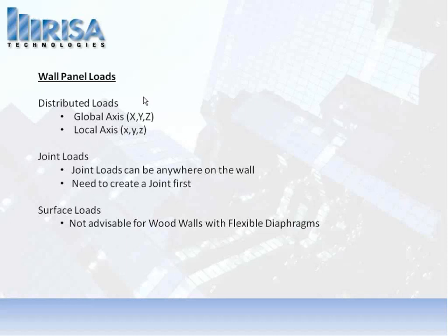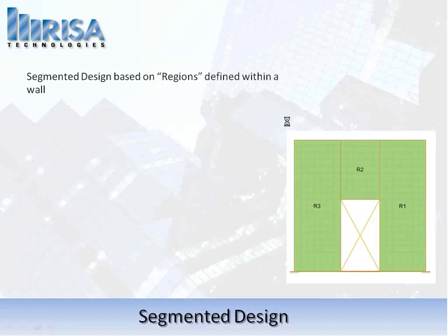So distributing loads out of plane, like for example, if I was just sort of blanketing wind load on that, it may actually push it out of plane too much with a flexible diaphragm. Maybe with a rigid diaphragm it would help us distribute the loads a little bit, but with a flexible diaphragm there's actually no real diaphragm behind the scenes, it's just a distribution of loads. So we'll talk more about diaphragms a little bit later, but the issue of surface loads, it can be done, but definitely you want to be wary and take a look at the results and make sure you're not pushing that wall over and not having enough stiffness there, okay, because there's very little out-of-plane stiffness, as I mentioned, compared to in-plane stiffness. Okay, so let's jump into some design information.